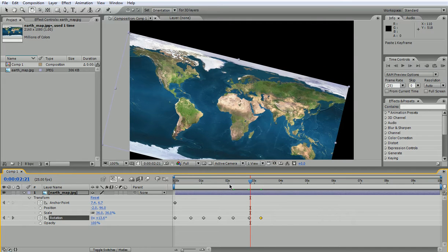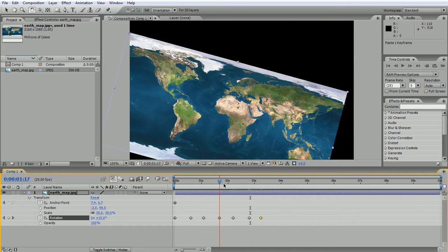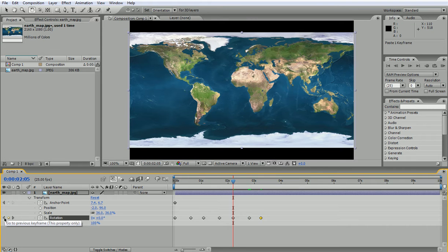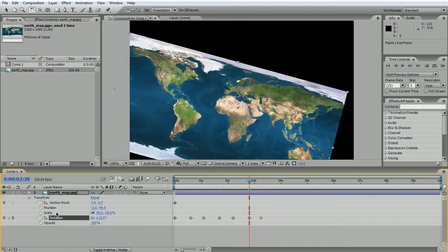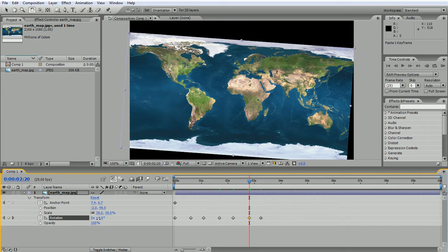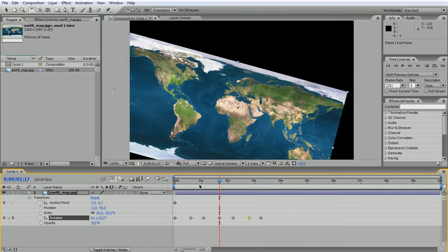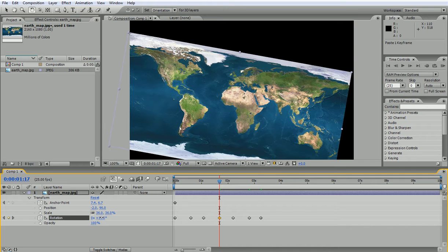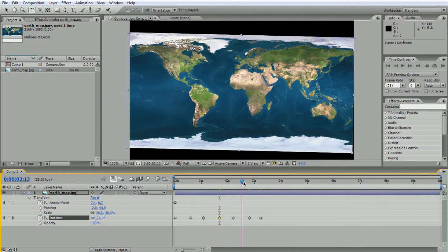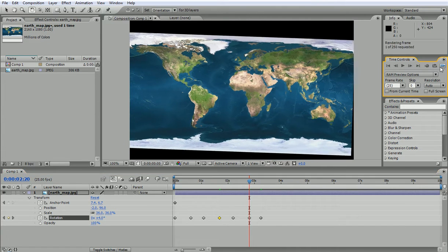All right. And this time here, I need to snap to my keyframe. I can press Shift, and that will snap to the keyframe because I want to change the value of the keyframe, not create a new keyframe. So to do that, you either press Shift to snap, or you can navigate between keyframes from here. All right, so I went there because I want to reduce the angle. So first we have, say, a large angle, and then less. Again, press Shift to catch that exactly. And then less. So if I played this,